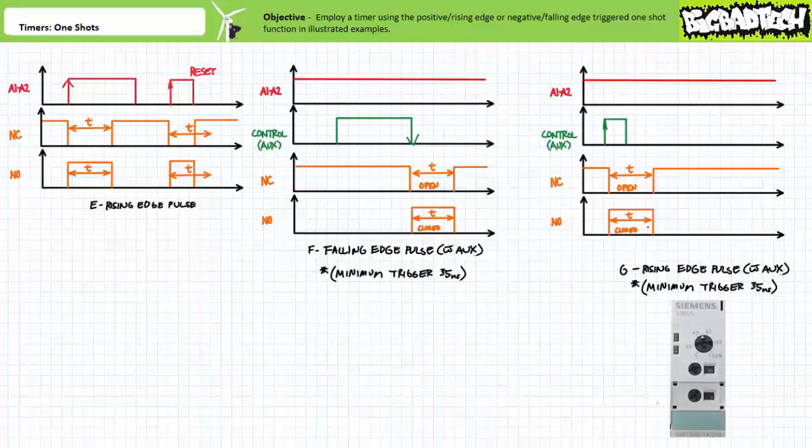You know you set up the pulse forming with auxiliary voltage function G correctly if you power up the timer, energize the controlling input, and see the output immediately change states. Wait 5 seconds for the one-shot period to elapse, and see the output return to the deactivated state.